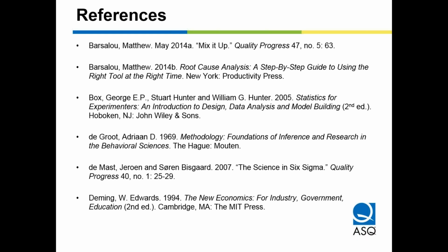I think air crashes. If you're interested in root cause analysis, read about air disasters. Read a book on it or go to Wikipedia. Why did the airplane go down? In many cases, it's a chain of error. You can think of the Alaska Airlines flight MD-80. This airliner went down into the Pacific. It was recoverable, and they discovered there was a jack screw on it with the threads completely worn. Well, the first failure was the stabilizer broke, putting the plane into a dive. Why did the stabilizer break? The jack screw was worn.